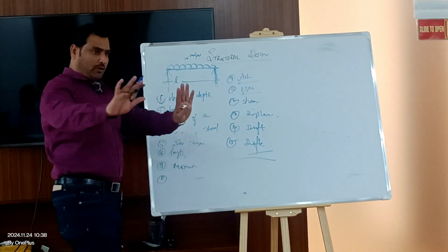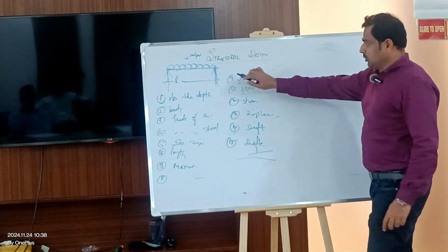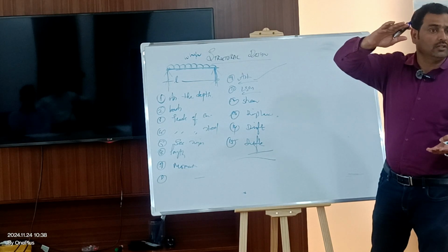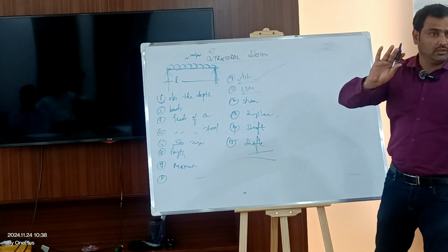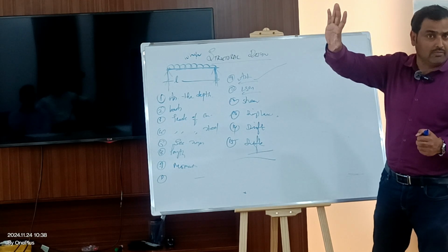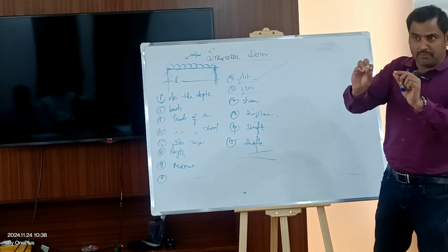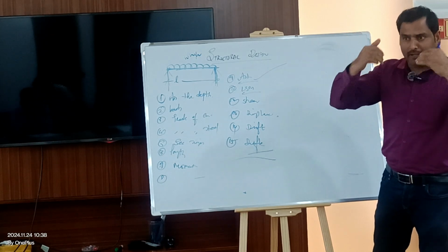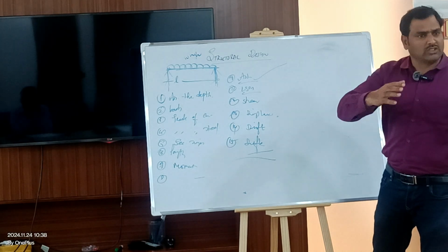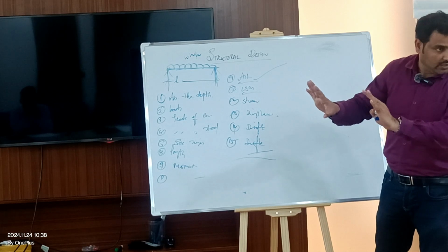Okay, I'll just reformulate but I'll give you the core answer. To design this concrete beam, what is required is the final section sizes and the rebar. So look at the core. If it is a steel beam, I need the size of the steel beam, right? And at the same time, I need the grade of steel. Whatever load you want to apply, dead load, gravity load, live load, seismic load, wind load, temperature load, you apply it. But finally, I need the section sizes, I need the grade, right?